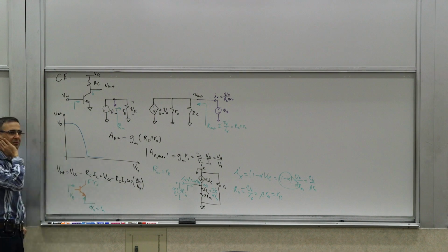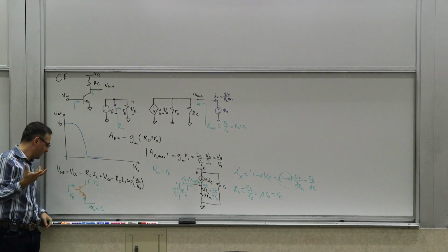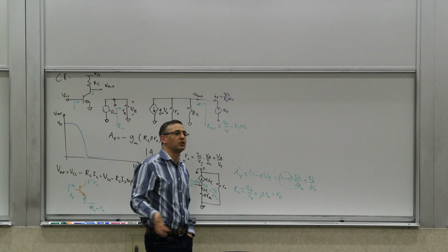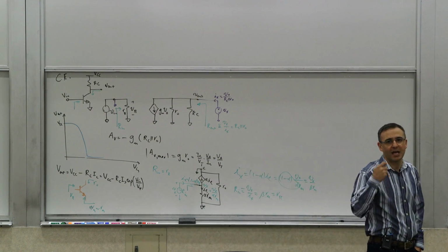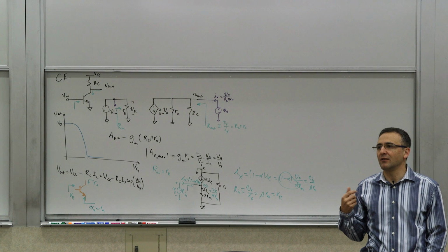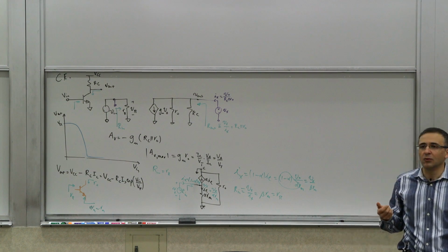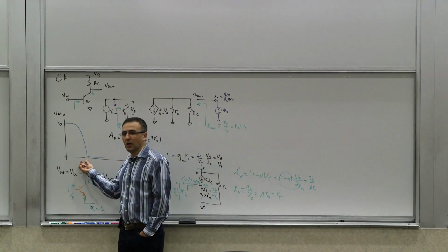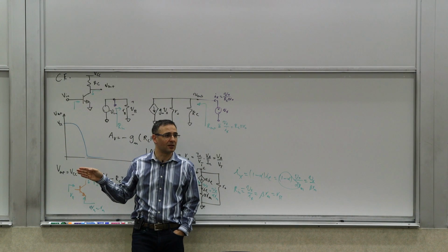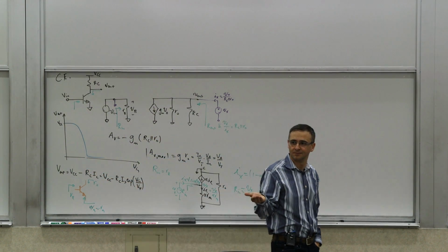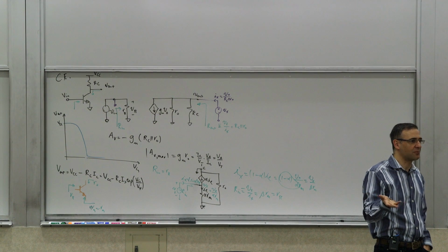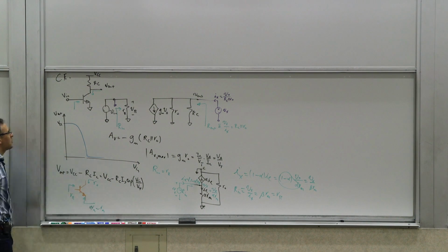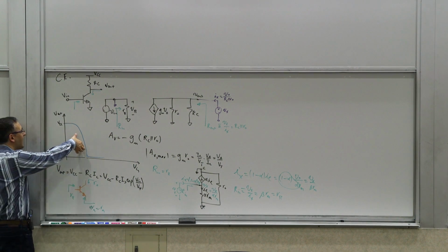If you look at the large signal behavior of it, there's a little problem, depending on what you're trying to do with it. If you're trying to use it as an amplifier, let's say to amplify audio, let's say you want to take this and attach it to a microphone and amplify the voice, what would it do to the audio the way it is? Well, it provides gain, but it's very nonlinear, right? It's an exponential, and exponentials are not particularly linear. So what can we do to linearize it? Why is it so nonlinear?